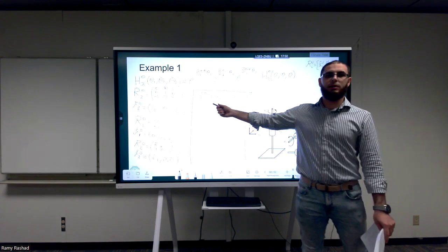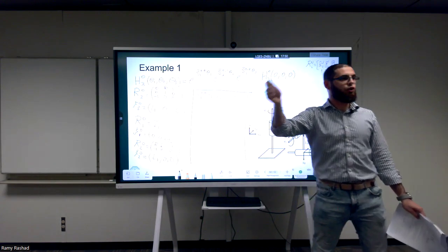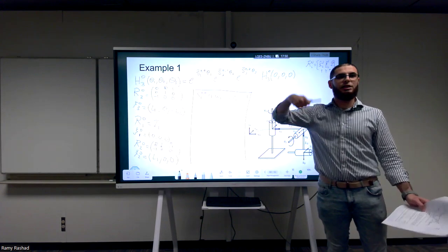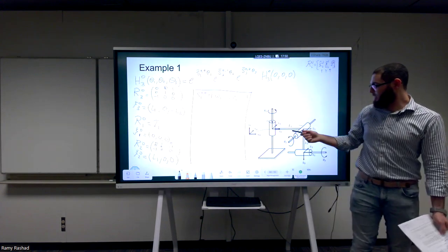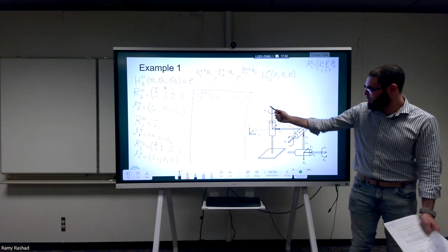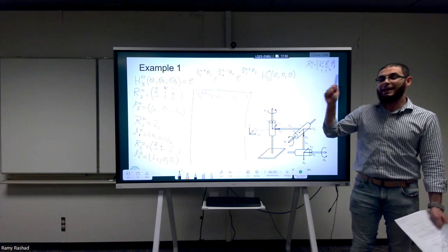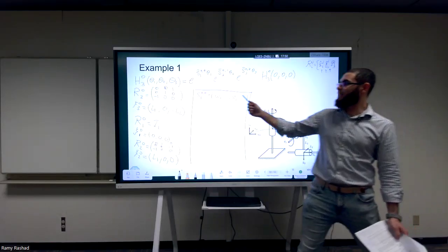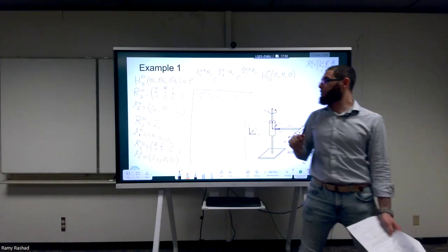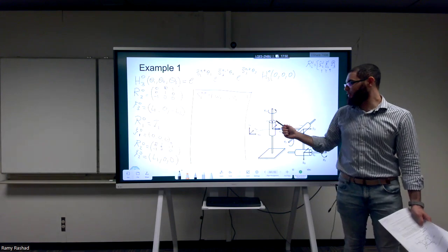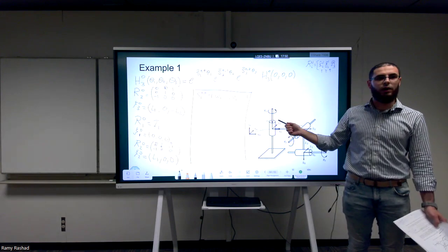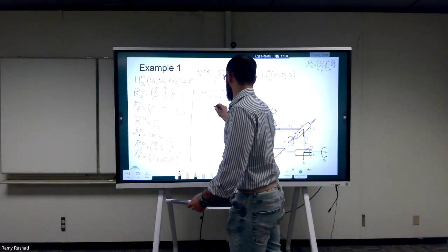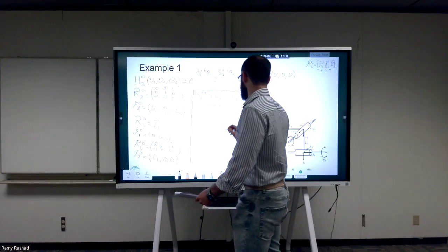The first 3 numbers, they should be a direction. They should be a unit vector. And it should be the direction around which this joint is rotating. What is the direction around which joint 1, theta 1 is rotating? Expressed in which frame? Very important. Expressed in the 0 frame. Okay. So around which frame are we rotating? Is theta 1? It's the Z, right? So this is the 0, 0, 1.